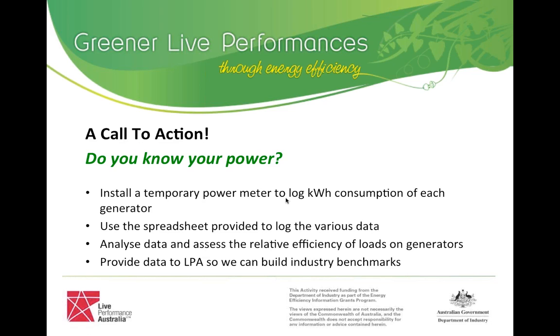So what we're hoping is that over the next year, we work with providers such as Coates and Aggreko and all of the other generator providers out there to be tracking your fuel consumption per generator and doing some metering to track kilowatt hours, so you can really see what your loads are on your generators and just how efficient you're going to be. So efficiency is going to come down to having the right number of generators for your job, having the right sized generators for your job, being as fuel efficient as possible, which comes down to loading those generators into that optimal load.